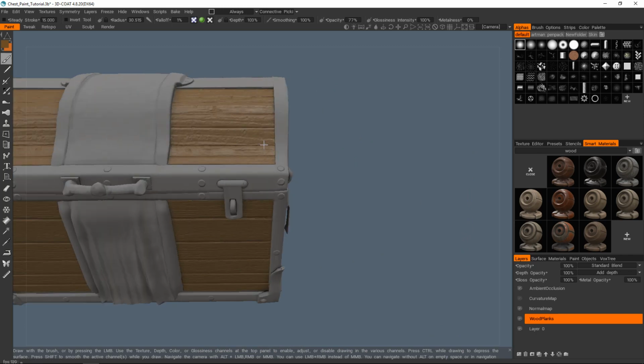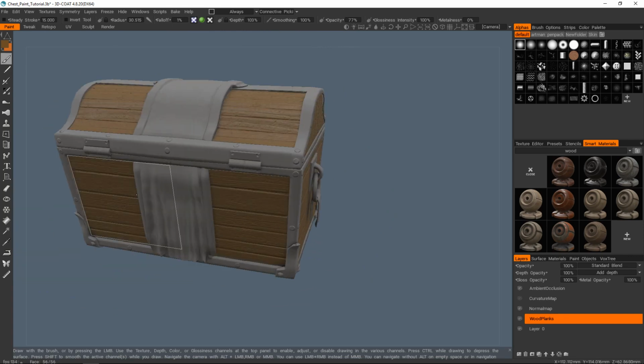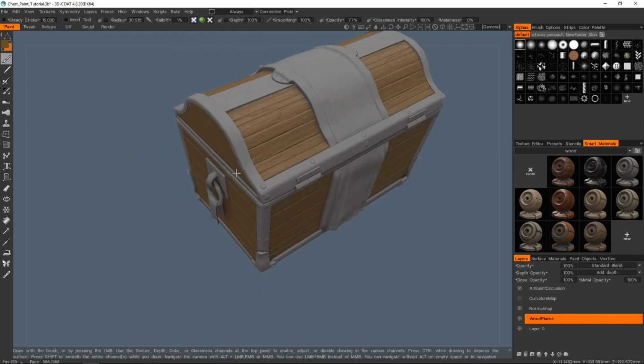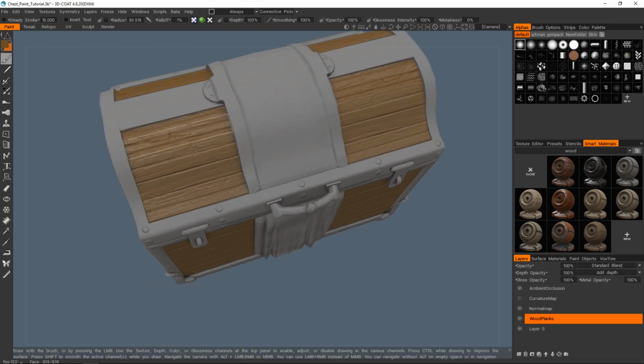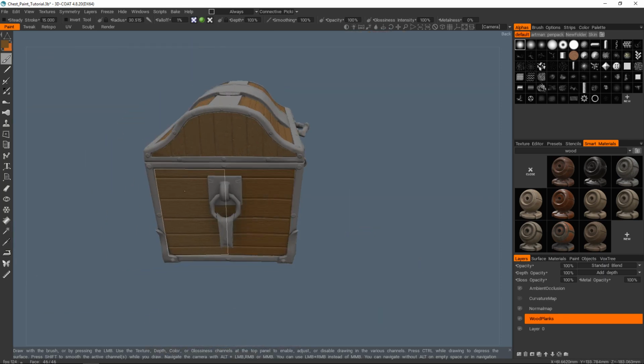again just using the polygon faces tool. You know, this kind of stuff is unbelievably quick to do. The only thing I would say to watch out for when you're using this mode is your opacity, which I've actually just made a mistake. It's on 77%. You want to make sure that that's on 100, because see, now if I go over things again, it's going to change the color a bit because it wasn't completely the color that I had chosen, which is my bad.